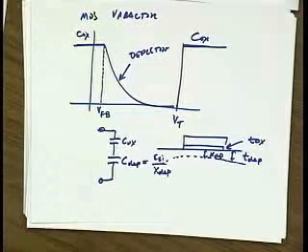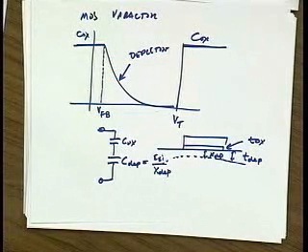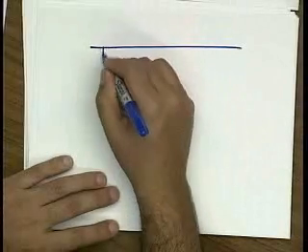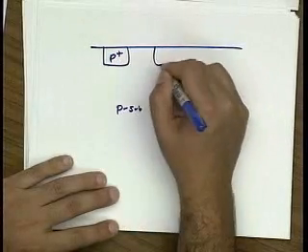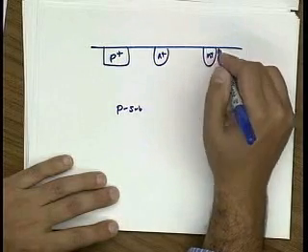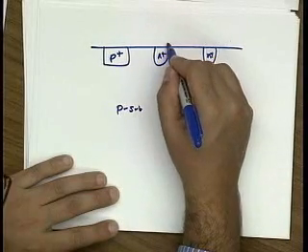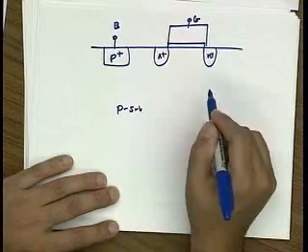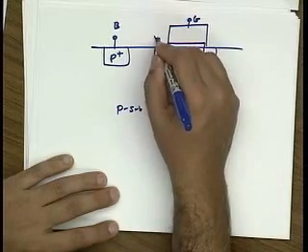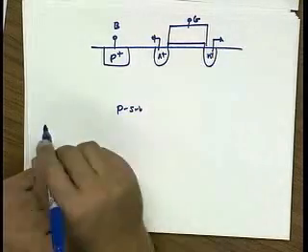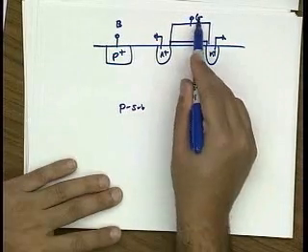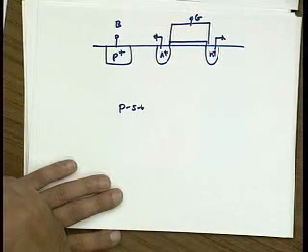Yes. So in all this, you've got the bulk connected to the drain source, correct? Yes. Yeah. So let me draw a better picture to make that clear. So this is my P sub. I'm going to build a capacitor like this. So this is the gate, this is the bulk, and I'm going to ground these guys so that I have a source for the electrons at high frequency. Okay? And so the capacitance is between gate and bulk, right?